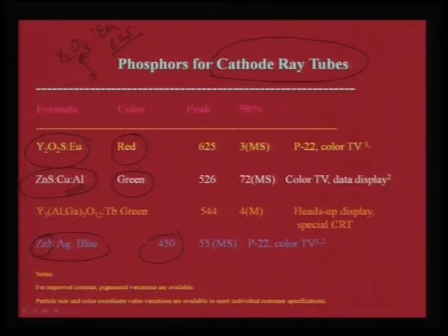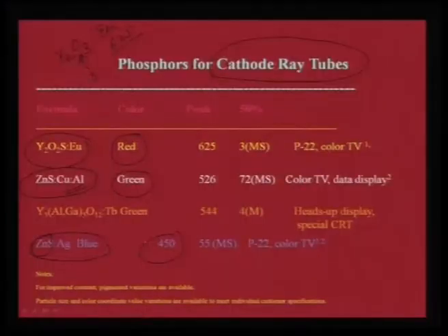So, in the whole issue of CRT phosphors, as you would see in the further slides, a number of examples are given. Many compounds have been traded commercially, and the most important phosphor of all is the zinc sulfide based one, because zinc sulfide phosphor is able to take care of both blue as well as green emission. The red is always unique to yttrium oxysulfide.